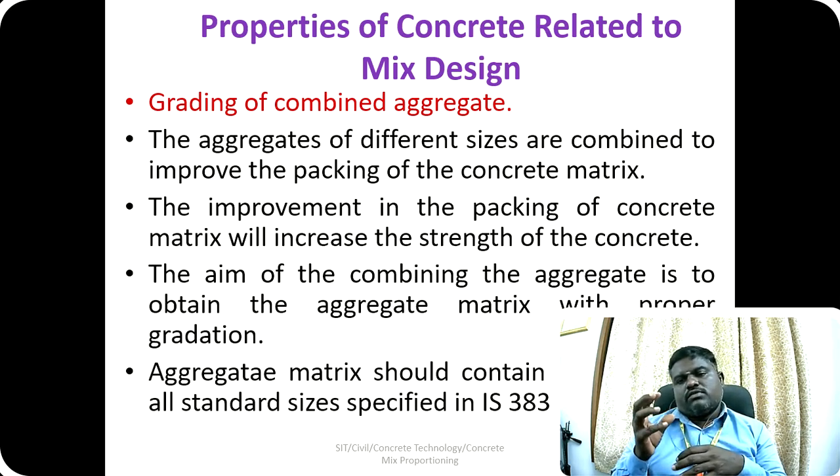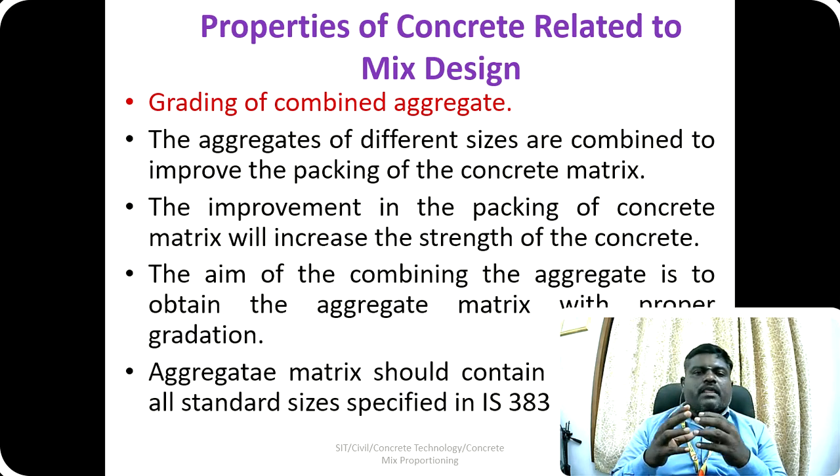The size of the crushed granite stone is higher. So the voids in the crushed granite stone are filled by the addition of sand, and after mixing this there will be some voids. They will be arrested by the addition of cement. Similarly, if you are using different kinds of aggregates, then the packing of the concrete will be enhanced.